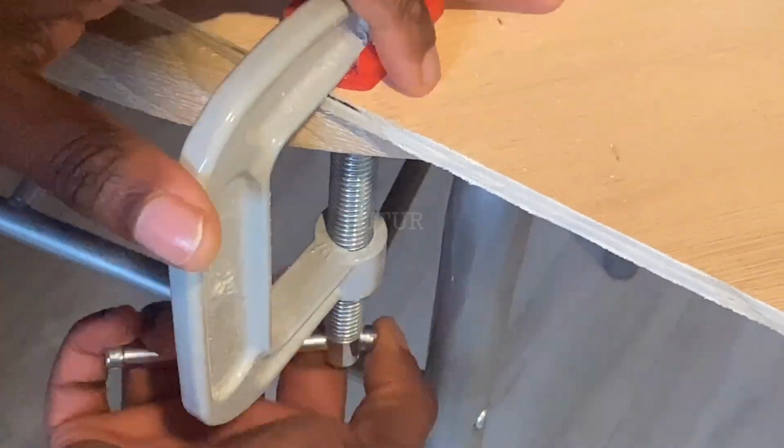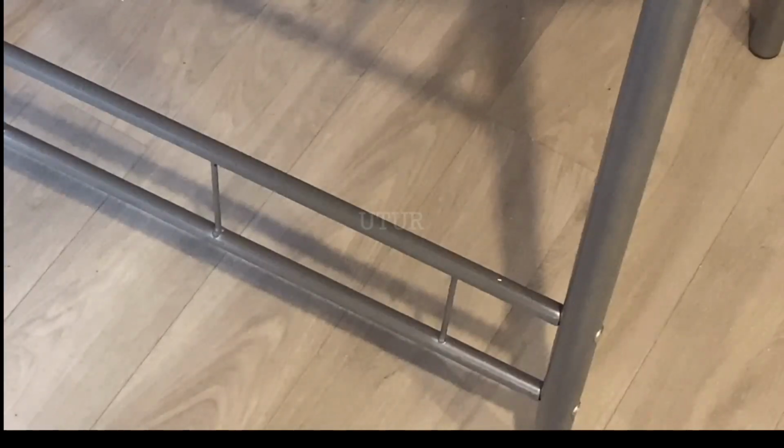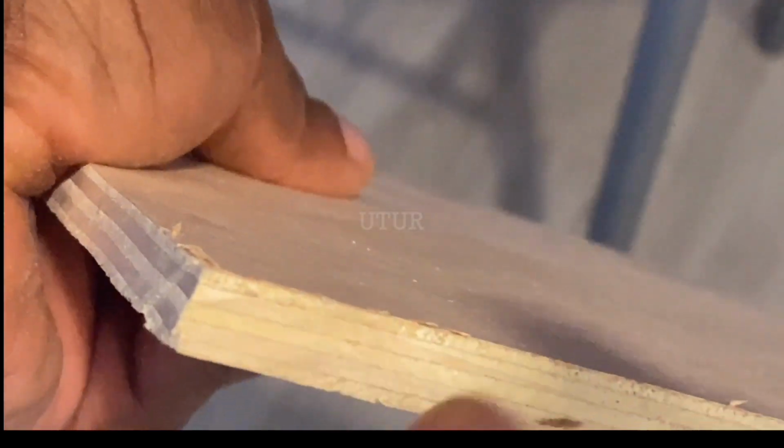And trust me, this stripped off bit is not the best looking piece on camera, but it looks a lot better in person when you actually visually inspect the stripped off piece. And as you can see, it's not the best looking quality cut, aesthetically, but it's better off than the binded cut that we had previously. At best, the blade has just done slightly below par of medium cross-cutting and ripping of the hardwood plywood. A combination or general purpose blade would have done a much better job with respect to getting quality cuts.